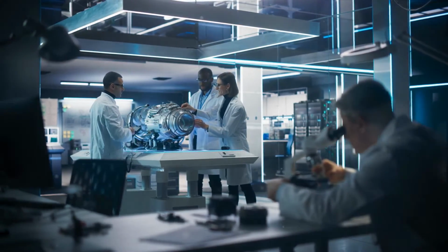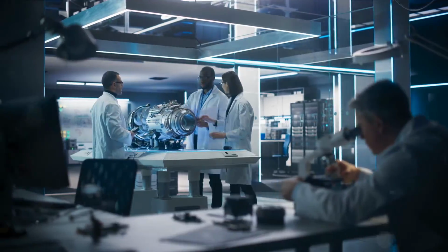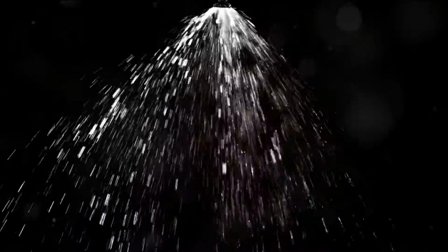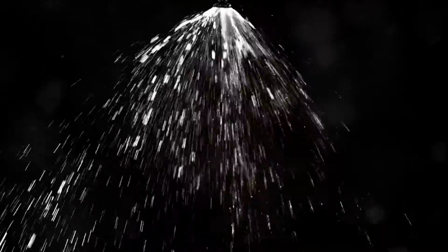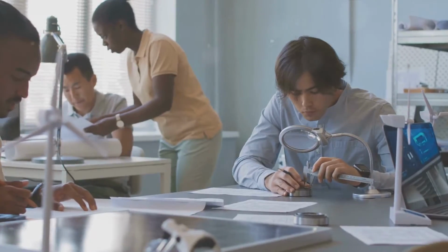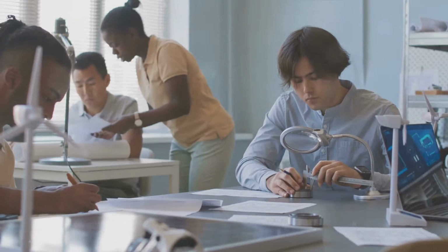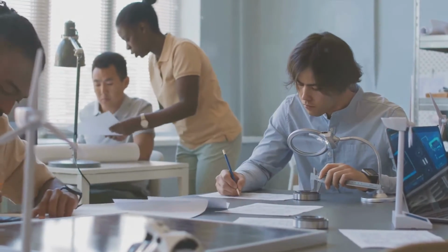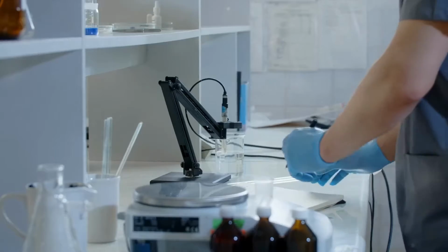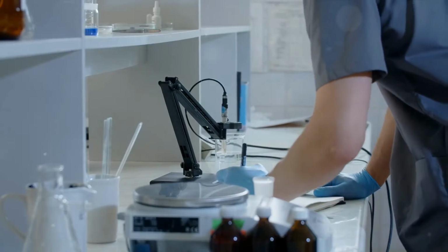Simulating real-world scenarios: spraying mechanisms. Spraying mechanisms are complex systems where discrete phase modeling, or DPM, can provide significant insights, especially concerning droplet breakup and evaporation. Setting up such simulations in ANSYS Fluent involves a detailed understanding of physical models and boundary conditions. The process begins with defining the type of spray, the properties of the liquid, and the operating conditions. This setup requires adjustments in the particle injection settings to accurately mimic the actual spraying process.